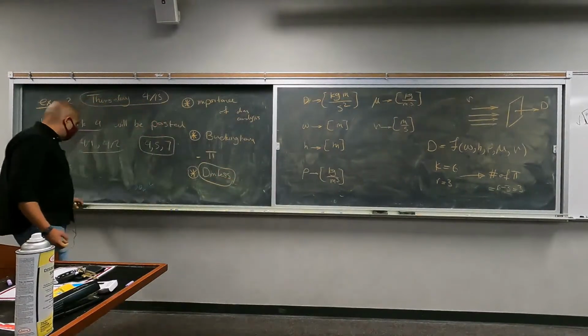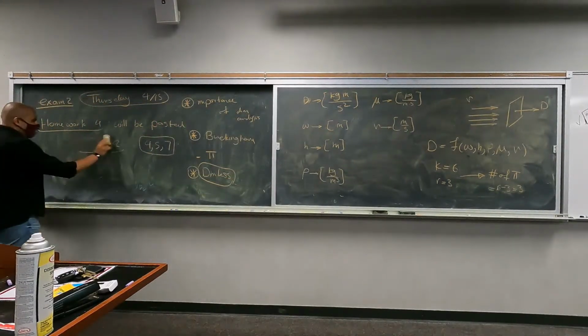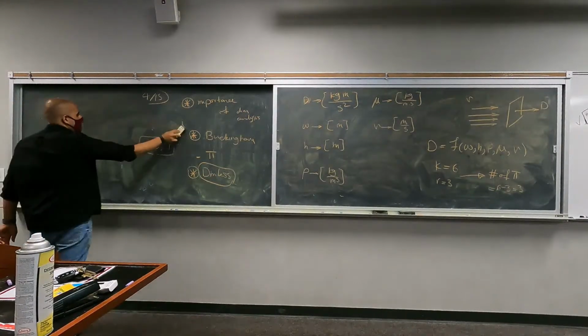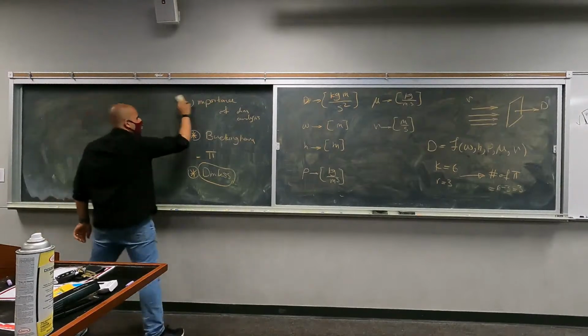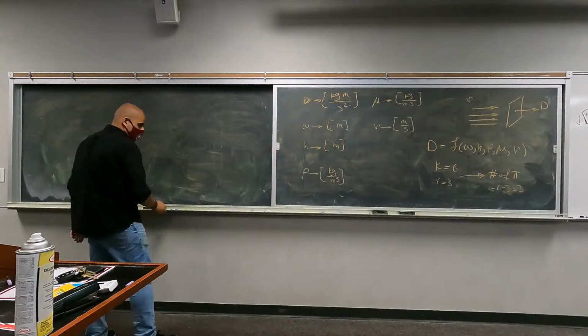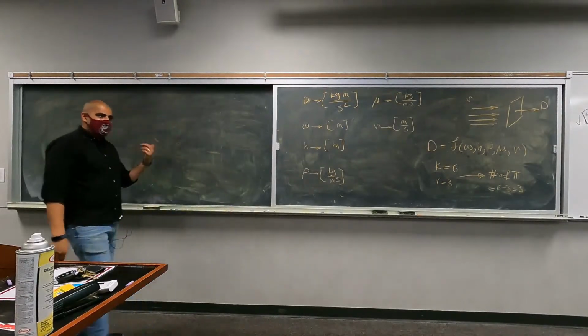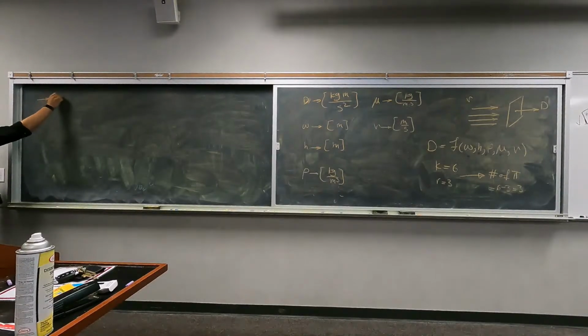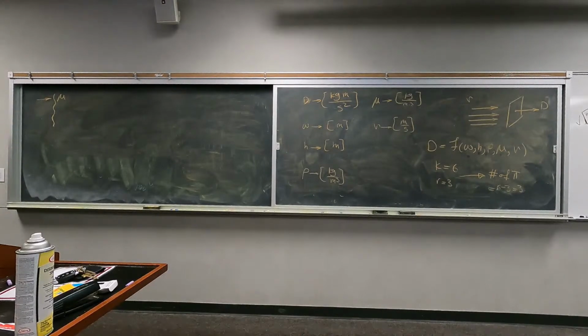But I would say whenever you have the presence of viscosity, it is usually one of your non-repeating variables, so you want to keep that there. We have 3 pi's, so we have to choose 3 non-repeating variables. So first one, viscosity. The second one I want to choose is the drag force itself, because that's the thing that we want to investigate.